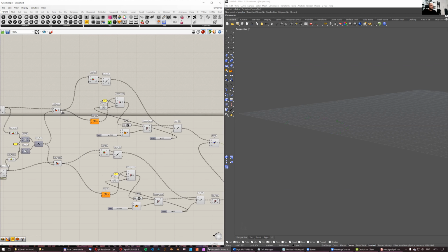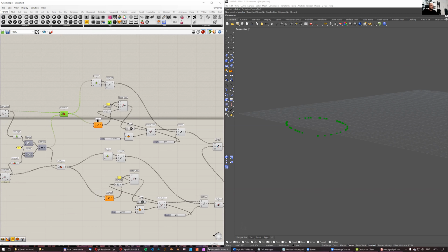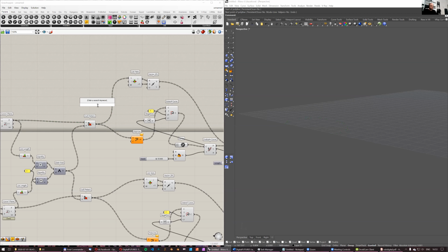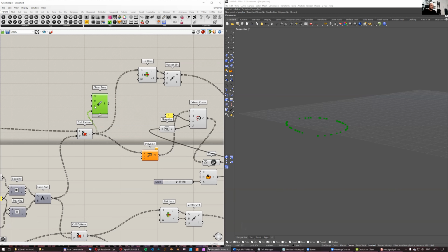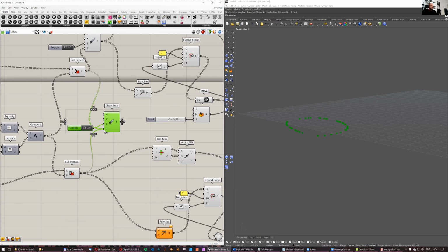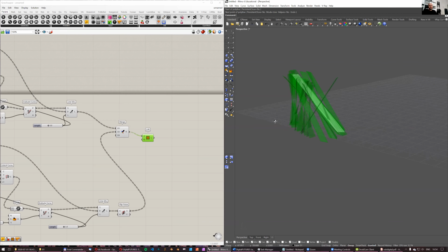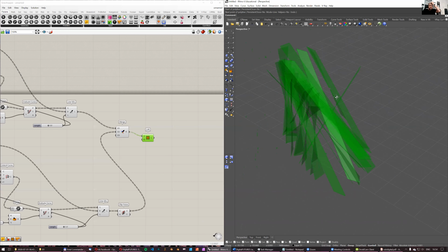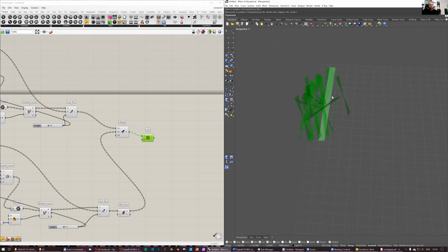And also what I can do, before I move on, is use Clean Tree, like this one, and that removes branches that contain nothing. I just need to switch it on here. This removes branches that contain nothing. I'll plug it here, and the same for the other one. So this will be pruned, and hopefully now it works. Okay, so only those legs that actually work well remained. And that's 27 legs only.